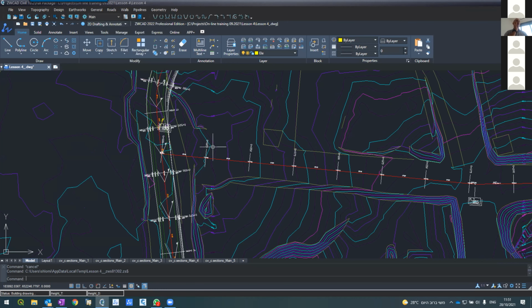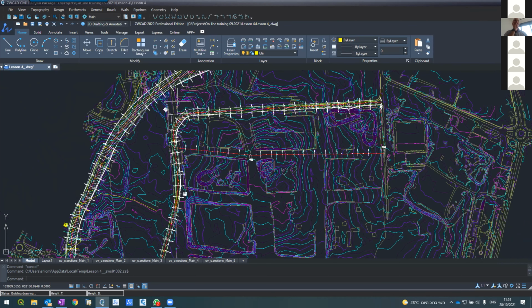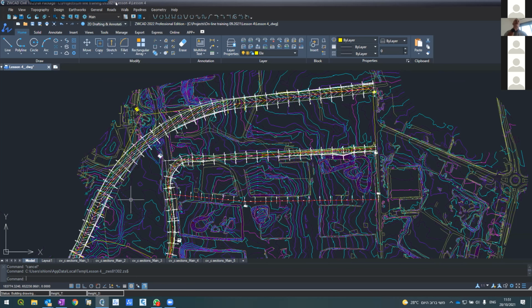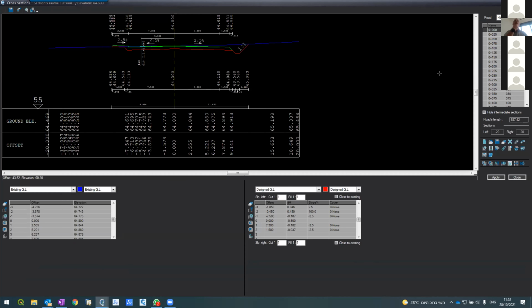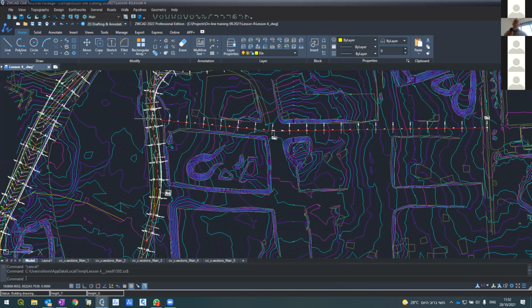So unfortunately, until we solve it, what you have to do is design the intersection manually, meaning go by the section and change the slopes in the intersection by yourself from the cross sections. Go to the cross section that goes into the intersection and design it, so that these contours and these contours go the same. Sorry, but this is the only solution I can offer today.